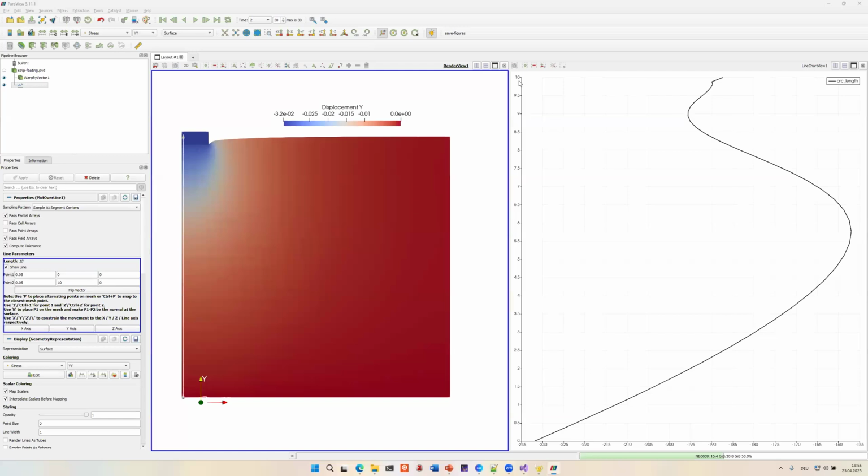But then, yes, we have done such things for foundations, right? So bearing capacity, modified Cam clay. We have applied a lot of modified Cam clay for this type, because usually it is of more interest for us for clay type soils, at least in what I have done so far. So my focus was more on that. It's Mohr-Coulomb and modified Cam clay, and the results there were reasonable. All right. Thank you, Jan.